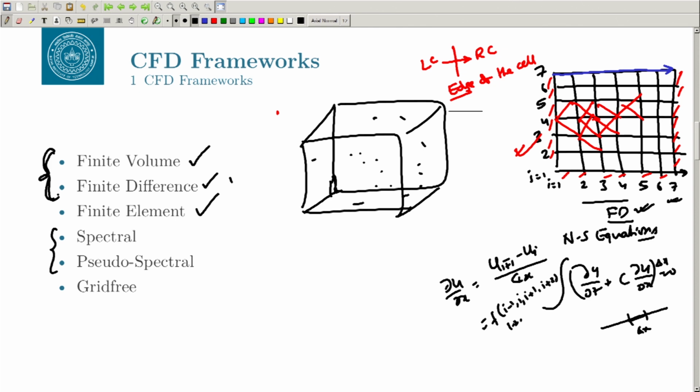Because of the non-linearity, the turbulence will develop and you will get more and more structures in the flow, and you might want to analyze what happens when you change the Reynolds number, what happens when you change the grid size and so on. If you just want to analyze this, you do not need a boundary layer, there is no wall, nothing. So, in this case you can utilize a periodic boundary condition. Whatever is getting in is getting out here, and on this side and this side.